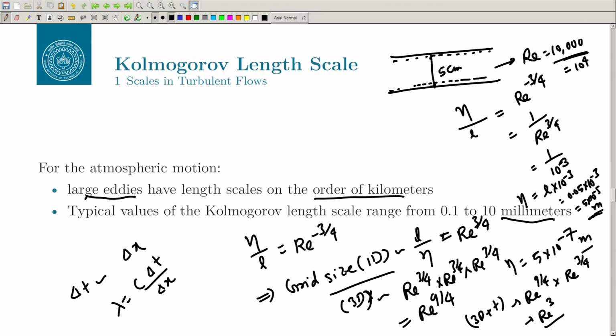But in that case, you may not know where that dissipation is cutting off. If you look at this E k versus k, it might be cutting off right in the inertial range, and then it may give you a completely wrong result. It may basically kill the scales which are very important, right. So, the coarse DNS is very dangerous. If you have a very coarse mesh, you can apply some kind of model there and make sure that you know where you are cutting your energy spectrum.